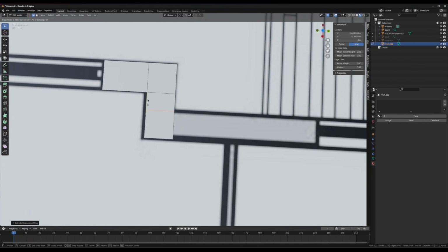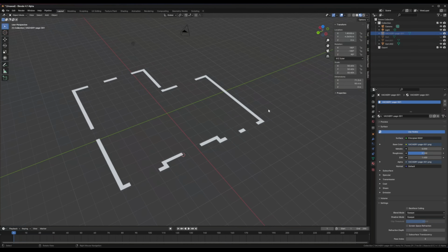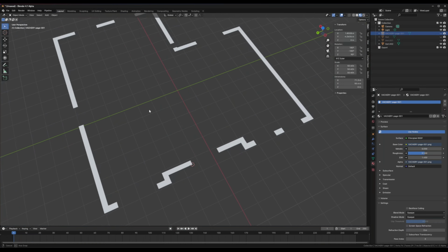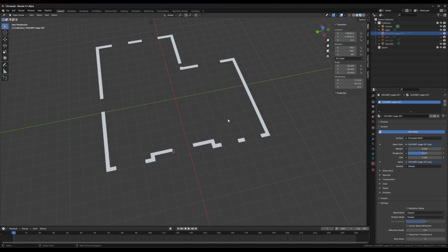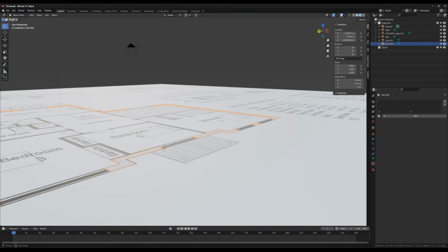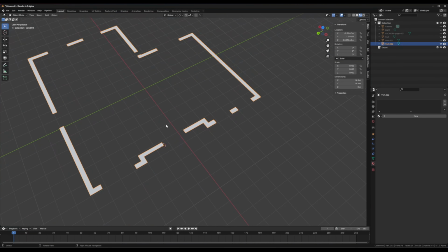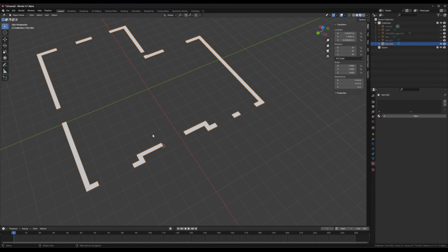Okay, so once that's all done, if we hide our main sheet now, we have all the exterior walls for the ground floor done. And we'll just press H to hide stuff so that we can see more visibility, and then Alt H to unhide stuff. Or let's say we want to isolate something. So let's say we want to work on this piece, we can do Shift H and it'll hide everything but this piece. And this is going to be especially useful when you're working on interiors, when you want to just hide everything except one wall you're trying to make a shelf on or something.